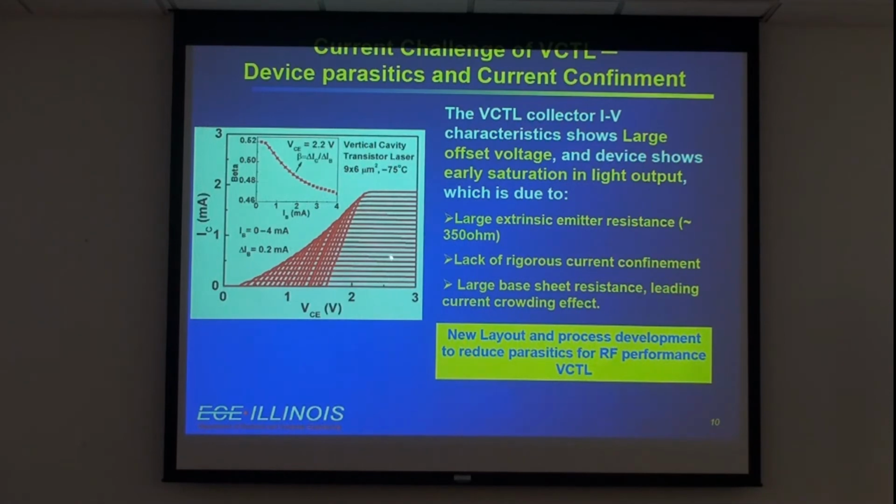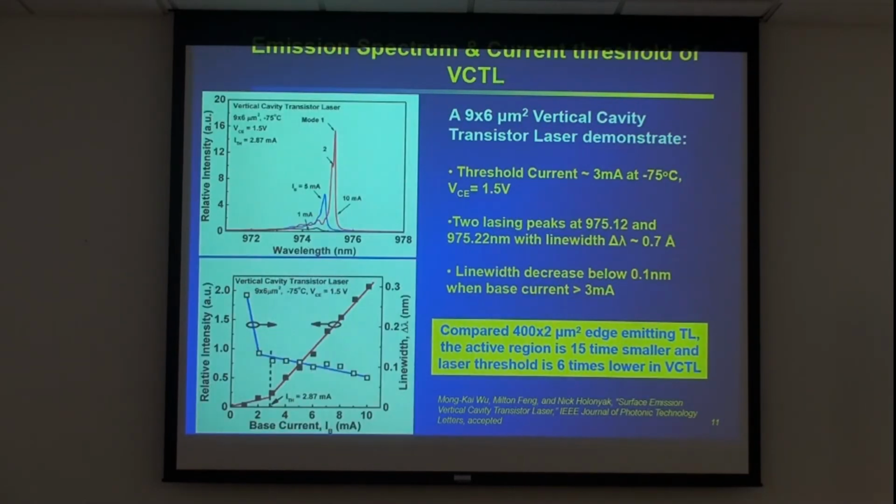But if you take it point by point, you can see a beta decrease from 0.5 to 0.45 around here, which is an indication of the change of the recombination rate. That means stimulated emission was enhanced. And here is the typical data we took from the spectrum.